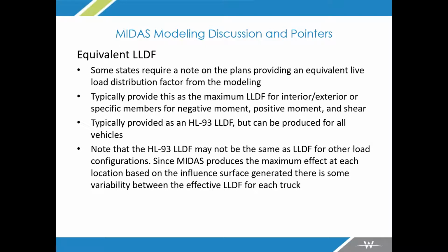States a lot of times want to look at this so that, if they wanted to take it into a very simplified girder line approach, they could manually input that distribution factor and run a girder line to check things as a conservative number. So really, we want to be conservative when we're reporting these so that they could use it for that purpose. Now, again, it's not really quite true.